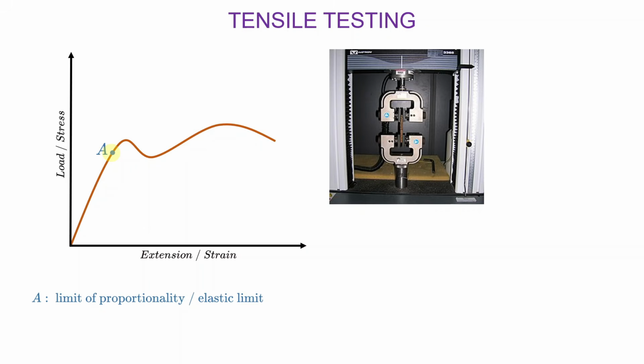And so the way you know where the limit of the proportionality is, is where the curve ceases to behave as a straight line, okay? So you will see that from 0 to A, you more or less have a straight line here. But beyond A, you no longer have a straight line. It seems to behave now like a curve. So proportionality ends at A, okay? I hope that is clear. So A is the limit of proportionality.